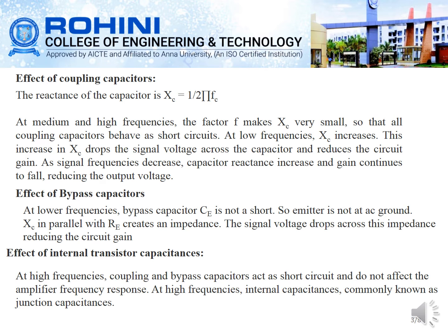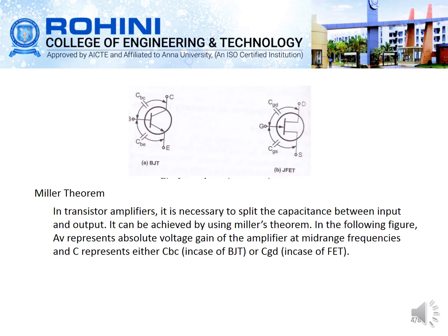And the effect of the internal transistor capacitance: at high frequencies, the coupling and the bypass capacitors act as short circuits, and they do not affect the amplifier frequency response. At high frequencies, the internal capacitances, which we call junction capacitances, come into play.